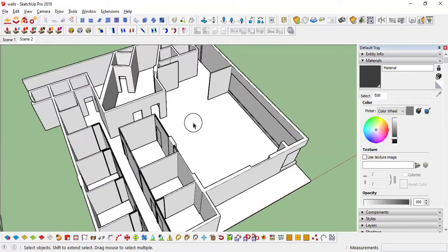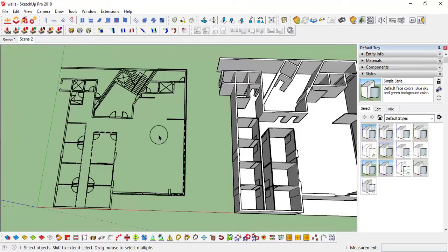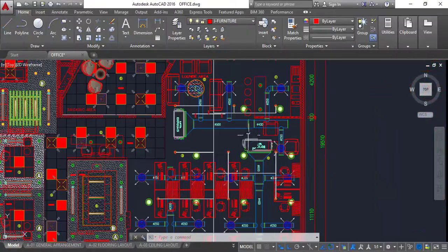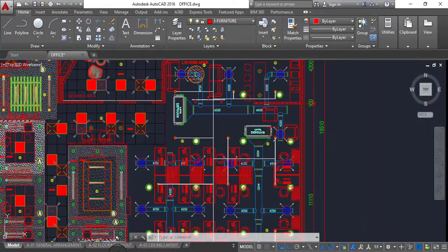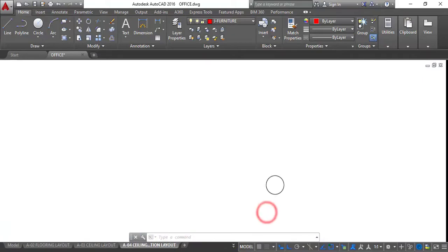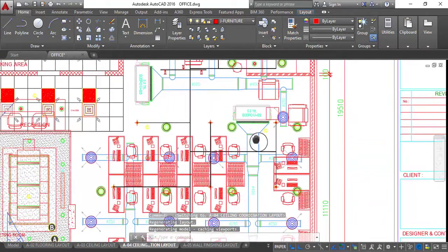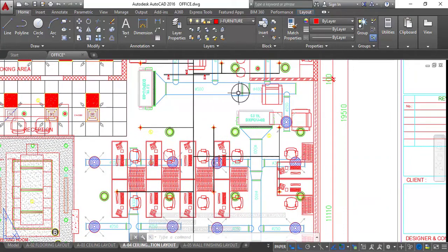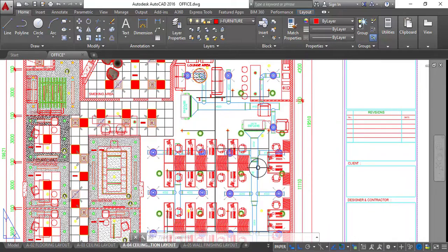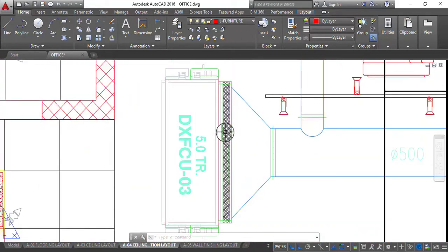For this video, we need to finalize the HVAC design, right? Okay, so if you observe the CAD file again, here they have mentioned a duct. We'll go to the ceiling layout, which is a little bit confusing. If you go to this layout, the blue color lines, these ducts are for HVAC or central air conditioning, and they use this kind of FCU units.